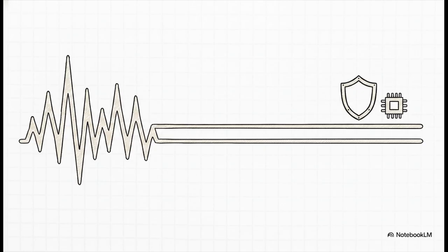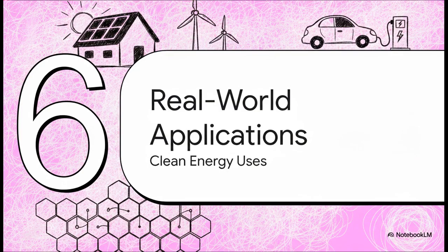When you first fire up a complex power electronics circuit, you get these startup transients, essentially momentary electrical blips and spikes as the inductor charges up and the PI controller gets its bearings. But as you'll see, both the input and output voltages stabilize incredibly fast. It rapidly locks right into a steady-state power delivery, ensuring that whatever sensitive equipment is drawing that 320 volts is totally protected.